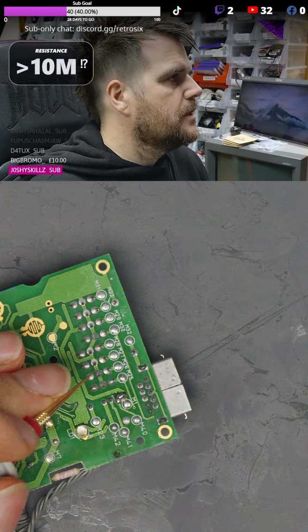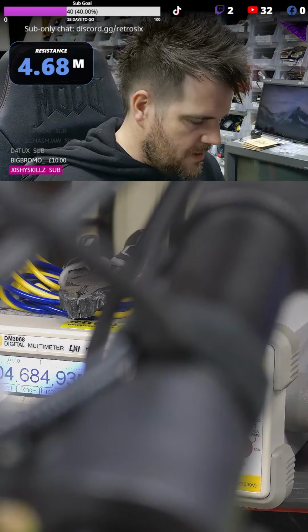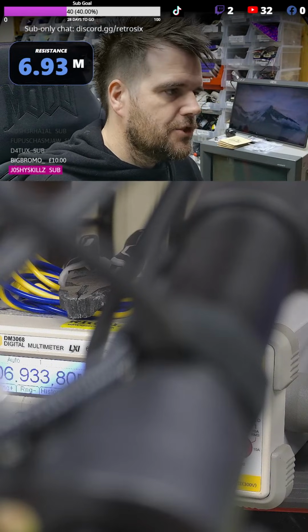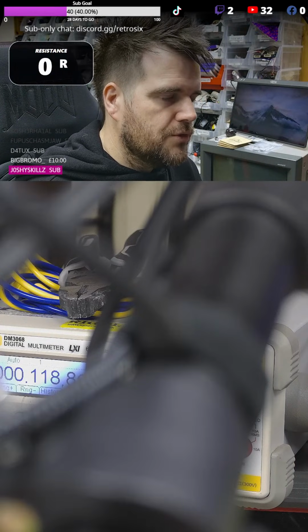And then if I look at this camera now, you can see if I probe directly on it, it's going to focus. Of course, this ridiculous setup to focus. Come on, focus on that. Is it going to focus? There we go. If I probe directly on the short, you can see we've got 0.1 ohms.